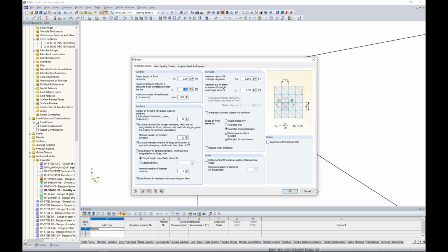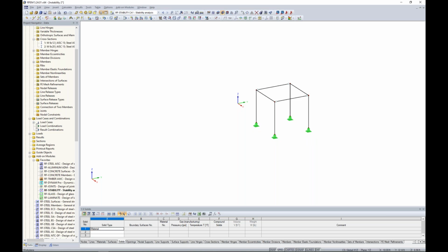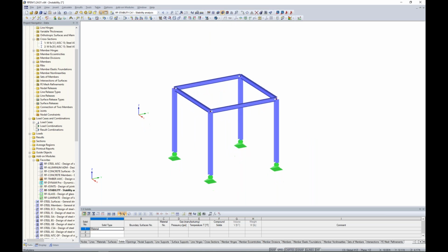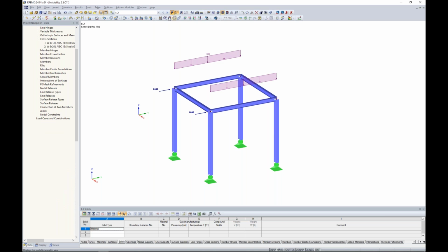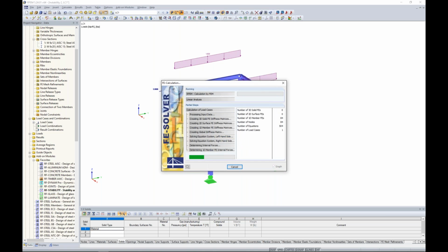So we'll leave this as default because clearly this distance is much greater than 0.003 feet, and all we need to do here is just grab this node and snap it to that column. Okay, so hopefully we've alleviated this instability. What we would do now is jump back to load case 1, remember with those same applied loads, and we'll begin to run the calculation.